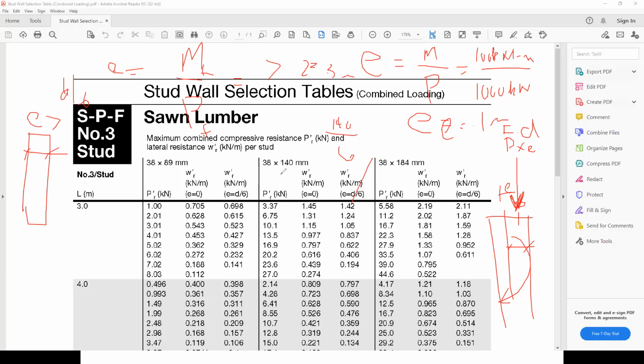That's all. Now, you'll hear this term somewhere if you continue in engineering, in your courses. You'll hear that if the resultant falls within the middle third, and D over 6 is what they mean by the middle third, when this is the maximum eccentricity, so that if I look at my foundation, and the resultant falls within the middle third, the tension here will be 0, and it will be like this.